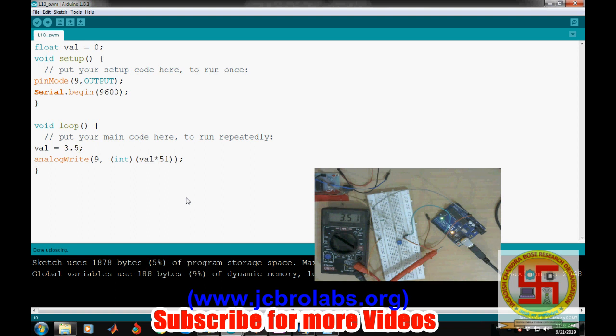Okay, so here we will write a small program in which we will be changing the intensity of the LED. It starts from 0 and slowly keeps building up and then slowly keeps building down. Okay, so that it gives you a flavor how to use this PWM wave for LED intensity variation. So this particular concept can also be used if you want to change the speed of the DC motor. Okay, and then we'll do it in the next video. So now let's write a program to change the intensity of LED up and down.